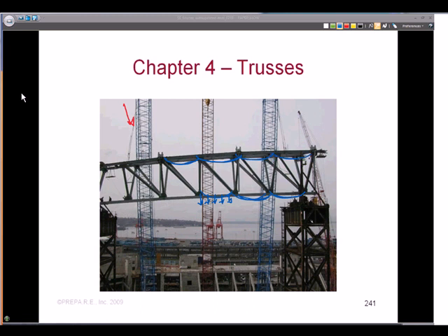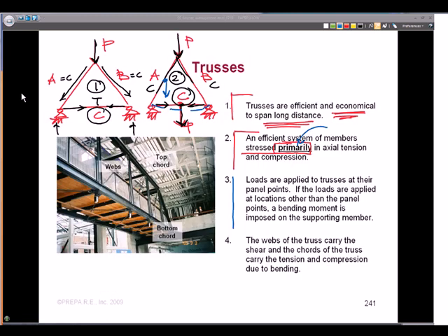On lighter, typical trusses, the self-weight probably won't control the design and have much effect, but we still need to consider it. So look for obvious point loads beyond just the self-weight of the member that's inducing the bending into it.